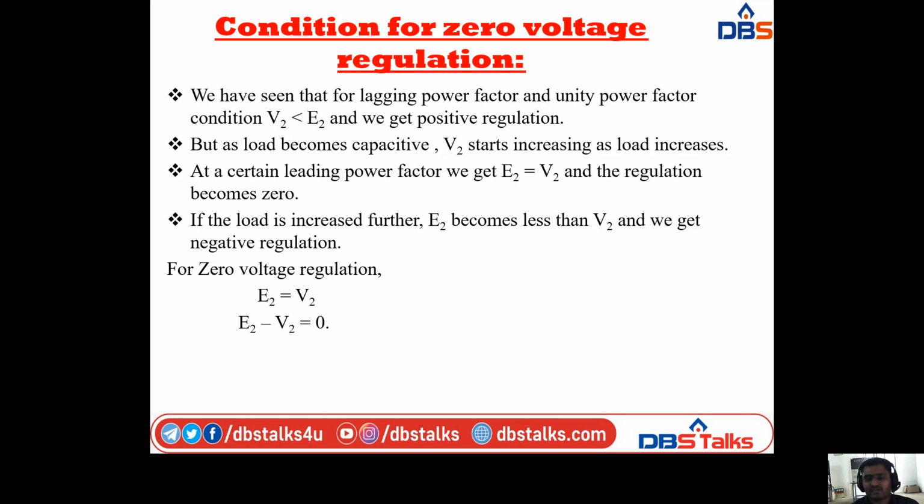If the load is increased further, E2 becomes less than V2, that is for the leading power factor, and we get negative regulation.